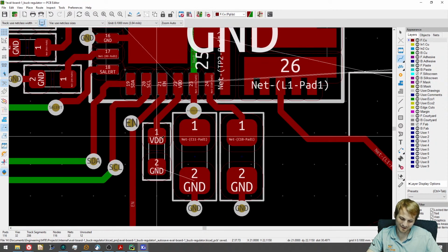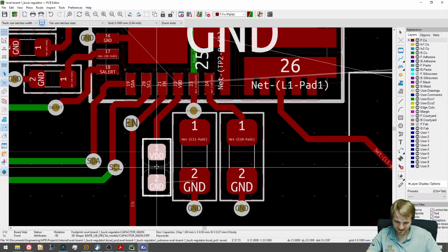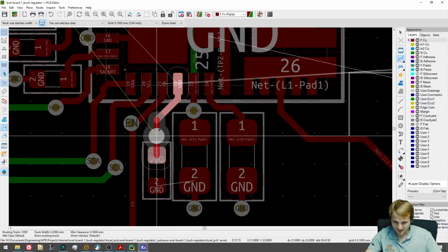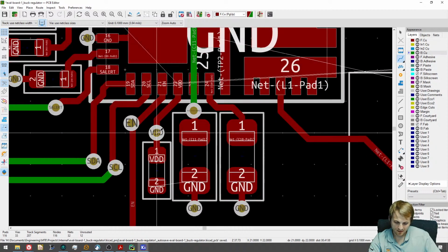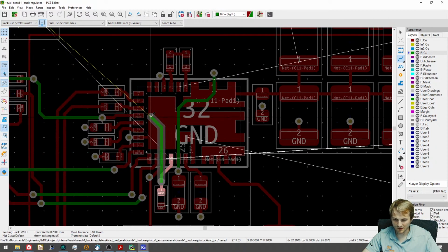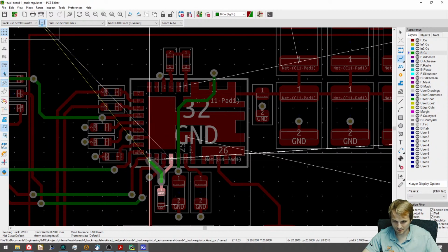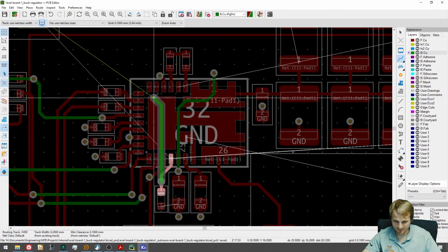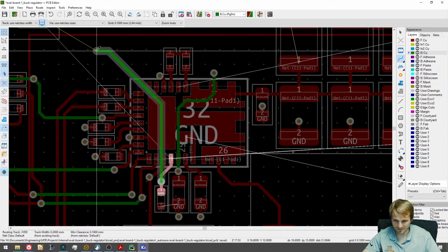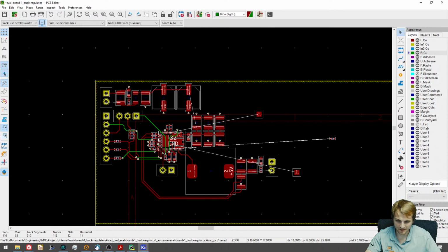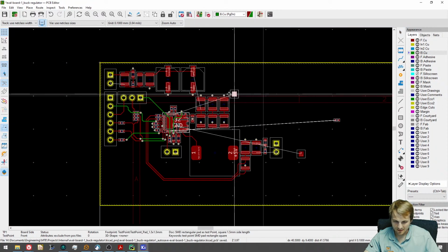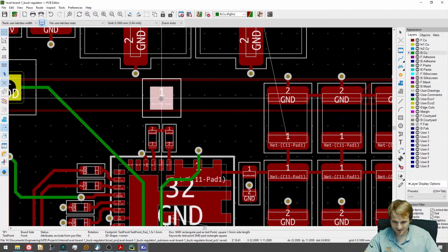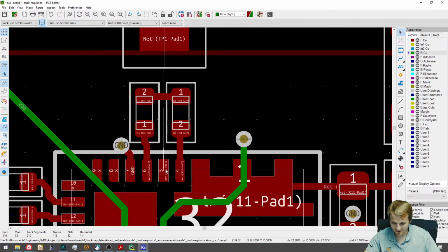Dang it. I'm gonna have to move this again. So yeah, we're not gonna have a choice but to move this down then. Okay, that wasn't too bad. And VDD, we can cut across here. I still normally don't like bringing bottom layers across, but with 4 layers, it should be fine. And then test points, which still this one makes no sense to me, why they put it in between here.